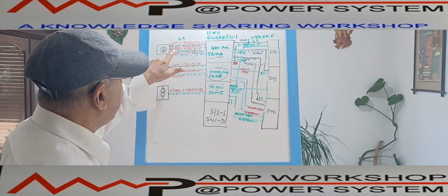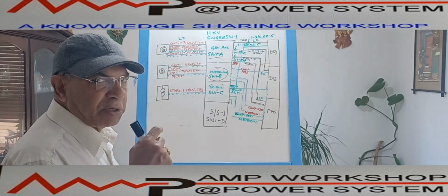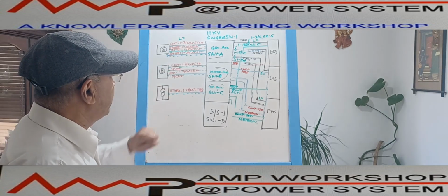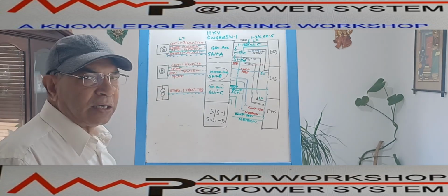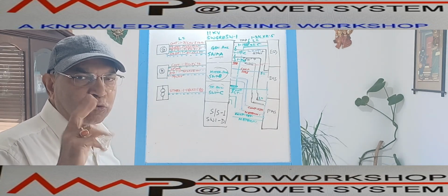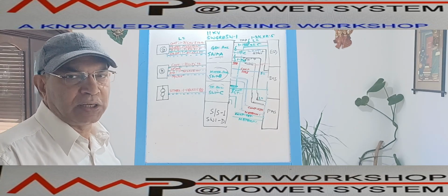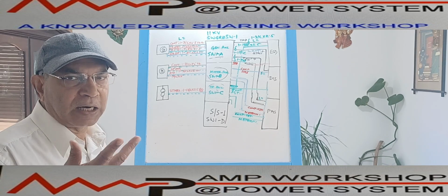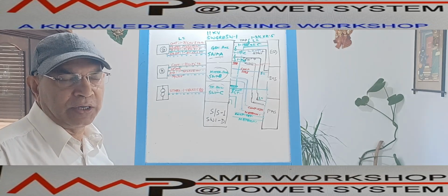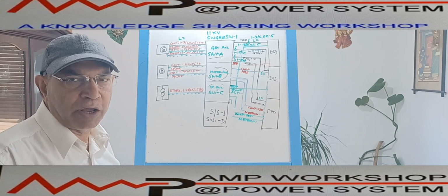One is a space heater cable, that is one 3-core 4 square millimeter, because there is one space heater which is heating, and this cable supplies power to it. Then there is the RTD. Now I am considering 3-wire RTDs. In each phase there are 2 RTDs, but normally we take 1 RTD as the temperature sensor. That means for 3 phases there will be 3 RTDs, and there are 2 bearing RTDs. So total 5 RTDs, and each is a 3-wire RTD. So 15 wires will be required.